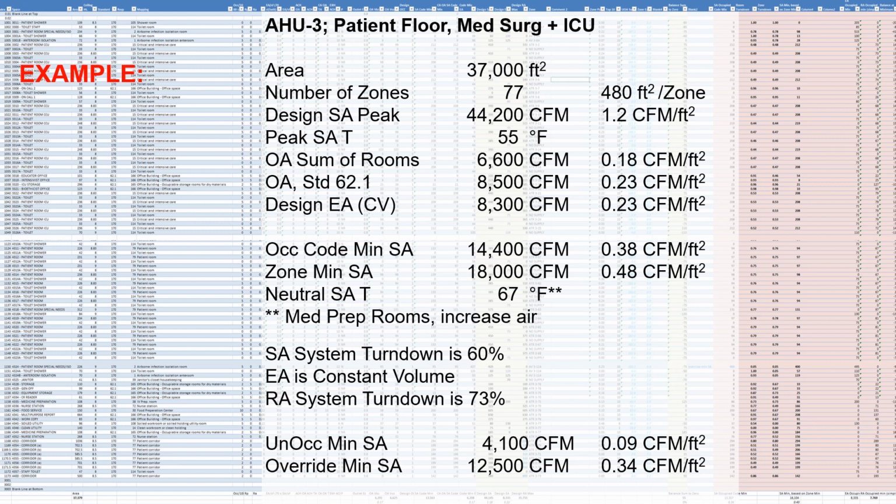However, at that point, I kind of always think that you should stop at around 30% turn down or 70% turn down. Just because in our experience in medical office buildings and office buildings, trying to get a system to ramp down from 100% to 30% is difficult enough. You'll run into challenges with coil velocities and fan capacities. VFDs can't really turn down more than 30%. And so trying to run down below 30% is really just difficult to do. So if you get down to 30%, consider it a win and move on from there.